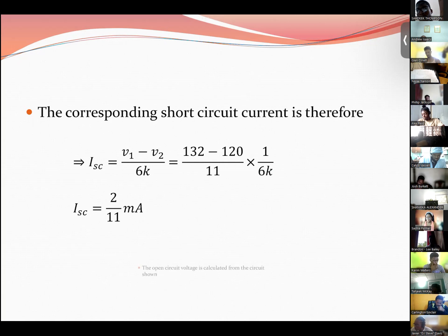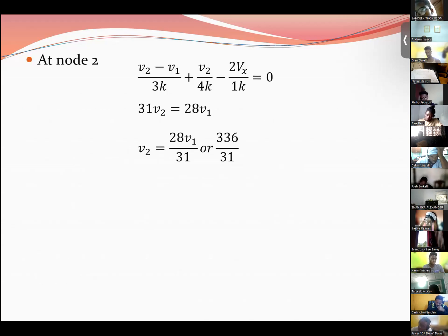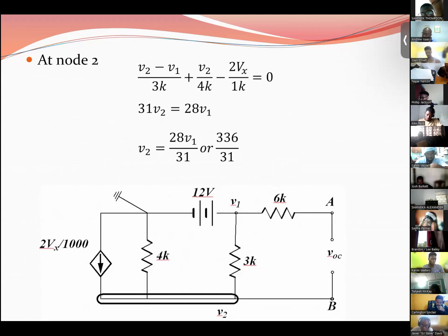We now need to find the open circuit voltage. So I'm going to open circuit that path, or the port. Between A and B, I have the open circuit. And this is why I say stick to the fundamentals, stick to the simple things. A while ago, when I went through it with Mr. Reed, we identified the 4 paths. With the open circuit, you realize that we have opened one of the paths.